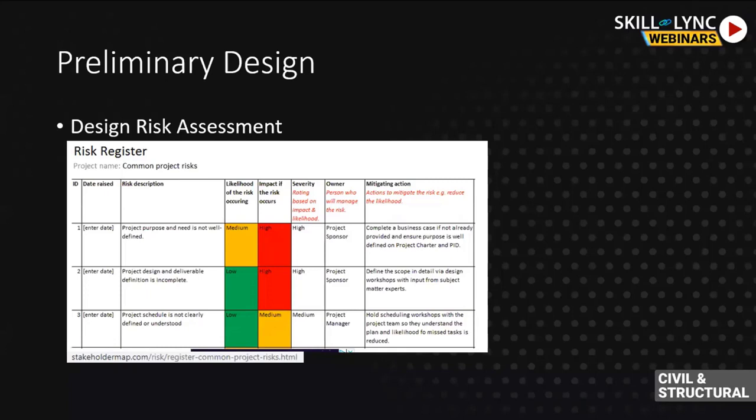How you want the cranes to operate. If there is some kind of demolition to happen, what are the temporary supports required? All these things should be captured and reflected on the drawings. As an engineer, you are responsible for any kind of accidents that happen on site because of not stating these hazards. These are the hazards that you should be aware of and think about while designing, during your preliminary design itself.